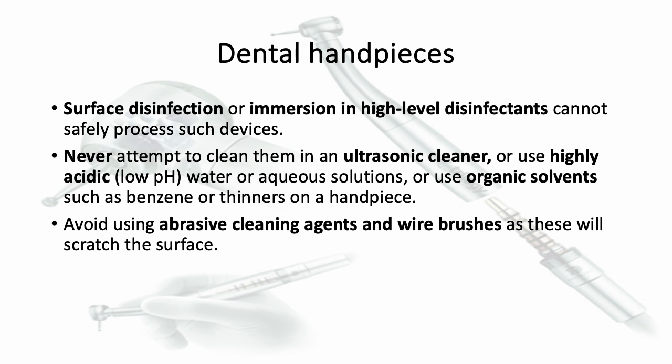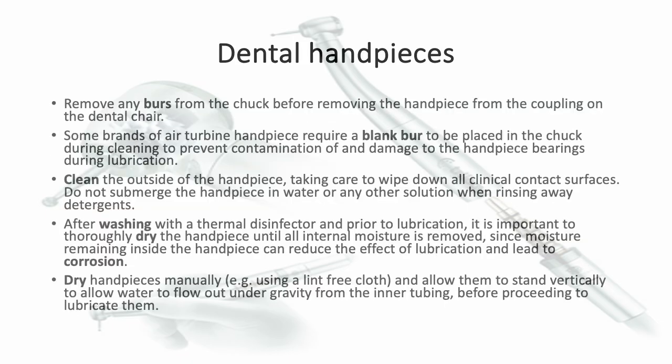And never attempt to clean them in an ultrasonic cleaner or use highly acidic water or use organic solvent such as benzene or thinner. Avoid using abrasive cleaning agent and wire brushes because these will cause scratches on the surfaces of the handpiece and damage them.